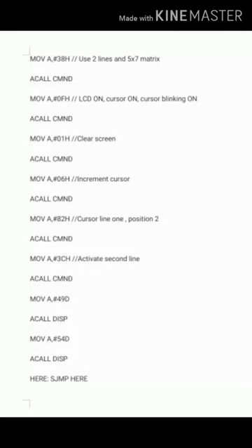When you call it, you are calling the function routine which will send this data as command data. So this data will be received by the LCD as a command. Once it receives this data as a command, it gets stored in the command register, and once it gets stored there, it gets executed as a command, right?